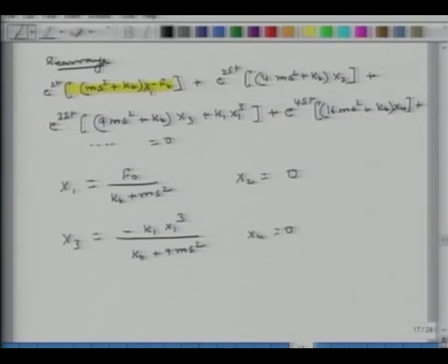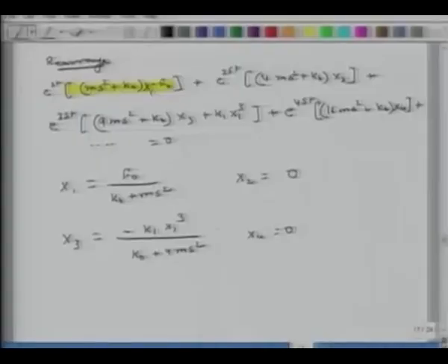So odd harmonics. What you are seeing is that just because you had one cubic term in the stiffness, you are generating an infinite number of extra frequencies for x, and that is all noise. So all the terms associated with x2, x3, x4, they are all noise.